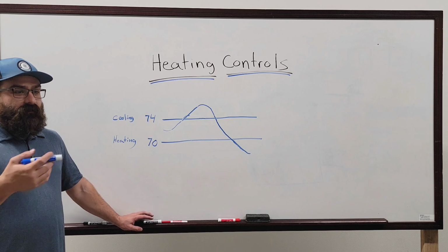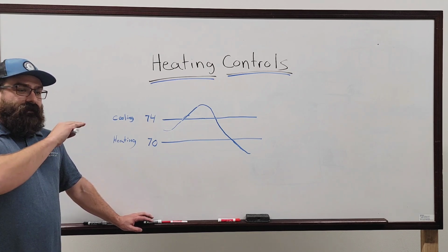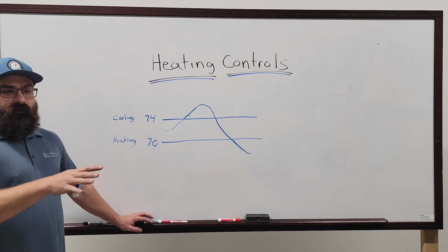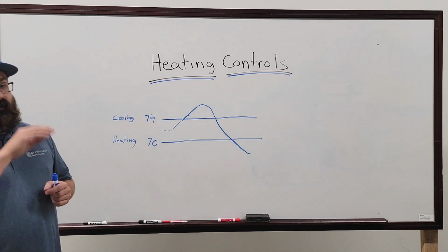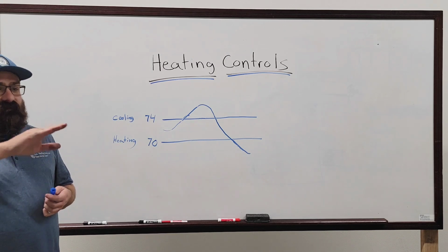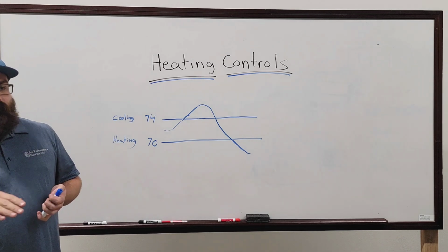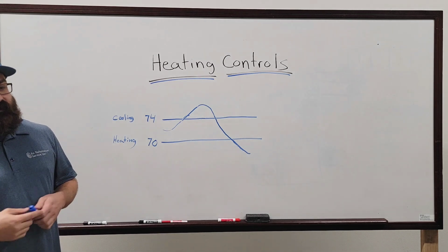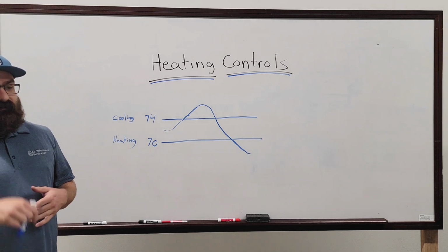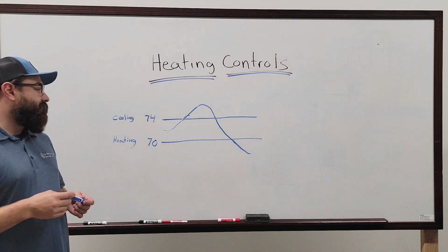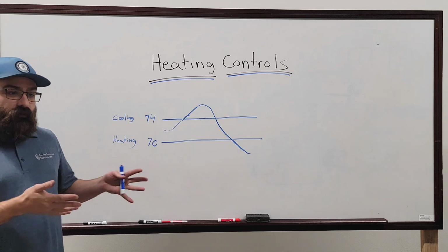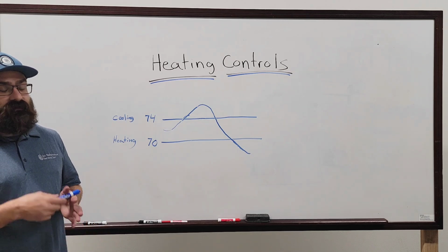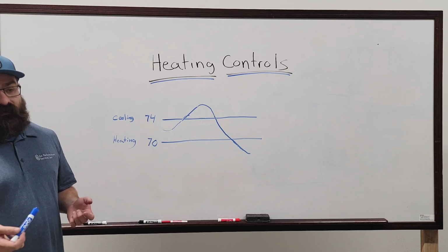Distech, same thing. They all offer a factory debugged and programmed and all that stuff, and then you just configure it and say, hey, it's got this much flow at this and this much flow at that, and you set your set points. It's got 2 stages of heat, 1 stage of heat, a fan or no fan. It's like checkboxes, right? And we don't have to program them 100%. They already have an application in them. You just have to define that application for your needs.